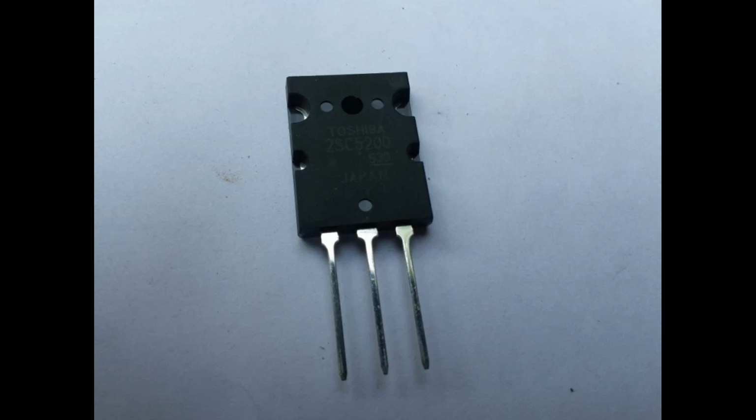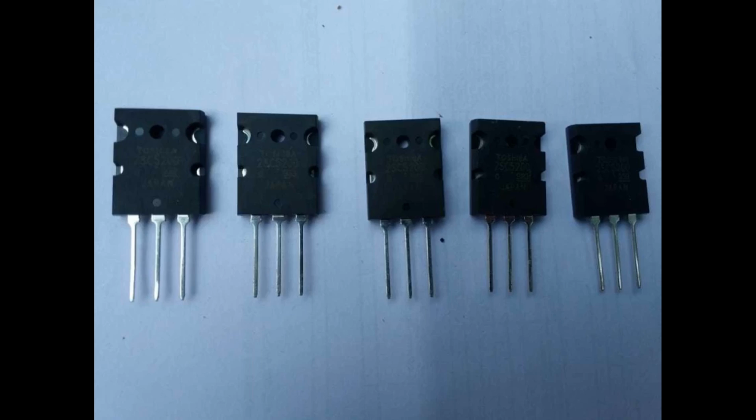When the output voltage rises above the desired level, the transistor reduces the current, and when it falls below the desired level, the transistor increases the current. Stable output: this feedback loop ensures that the output voltage remains constant and independent of variations in the input voltage, load conditions, or temperature. Linear voltage regulators are widely used in applications where low noise and simplicity are more critical than energy efficiency. They are commonly found in devices like microcontrollers, sensors, and linear power supplies.